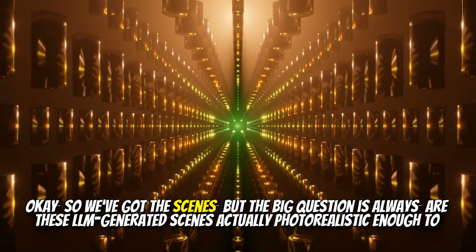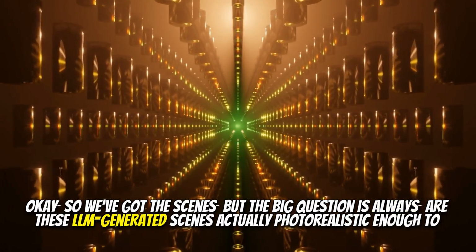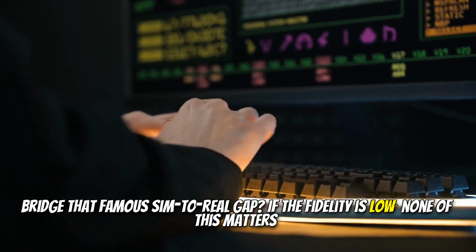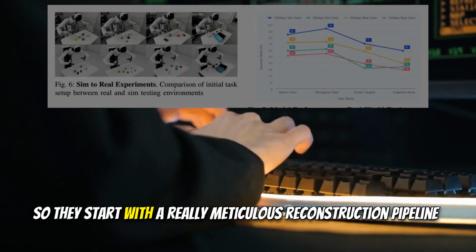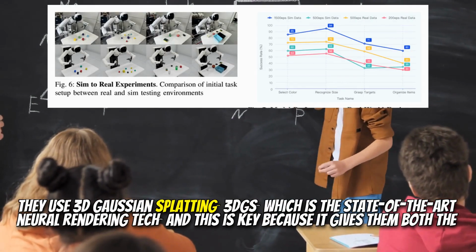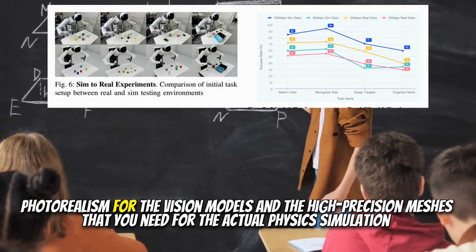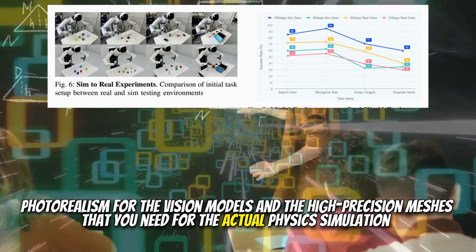Okay, so we've got the scenes, but the big question is always, are these LLM-generated scenes actually photorealistic enough to bridge that famous sim-to-real gap? If the fidelity is low, none of this matters. Fidelity is everything for sim-to-real. So they start with a really meticulous reconstruction pipeline. They use 3D Gaussian splatting, 3D-GS, which is a state-of-the-art neural rendering tech. And this is key because it gives them both the photorealism for the vision models and the high-precision meshes that you need for the actual physics simulation.